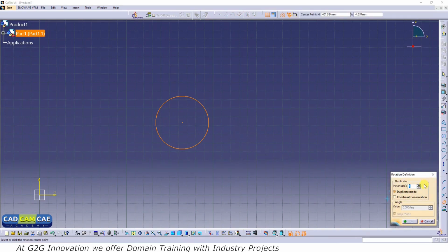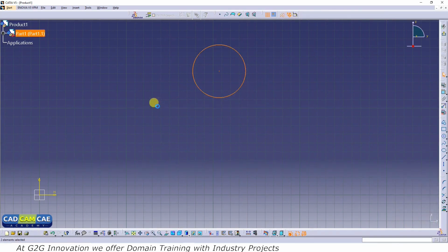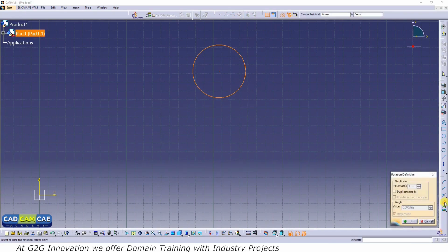Here you can see a pop-up window. You can create a duplicate geometry and rotate it, or uncheck it and rotate the original geometry. So let's try with the original geometry first. First we need to define the point of rotation, and then you can click one more time and define the arm which will help you to rotate the geometry, and this is how the geometry is going to rotate. So let's try one more time. Select the geometry, click on the command.